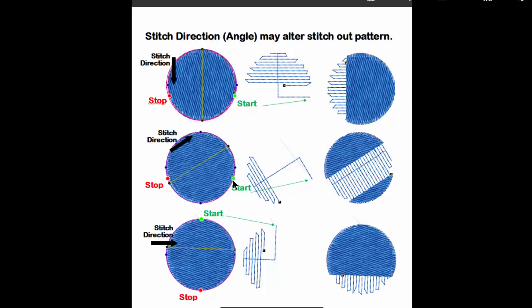The start point is still here on the right, so that starting point will begin right there with your underlay, and it comes and begins that, noticing that it is now stitching in the direction, the angle that we have set. And in this instance, it is going to come and fill this top side first, and then come over and fill this bottom side.